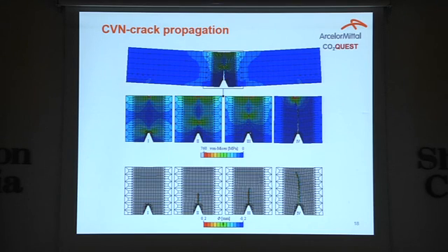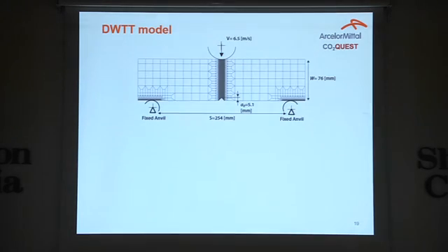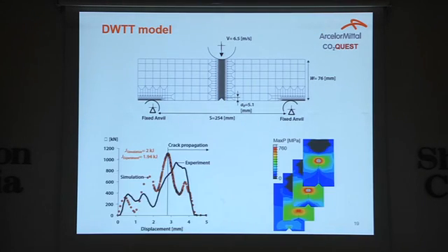And also we apply that to here. You can see some results of stress distribution and how the crack propagates. And then the last part, worth mentioning, we have a mixed mode crack, because of the impact we have huge compressive stress there. So when the crack hits, the compressive stress wants to find some way to propagate, which would be in mixed mode. We did it also for the drop tear test.